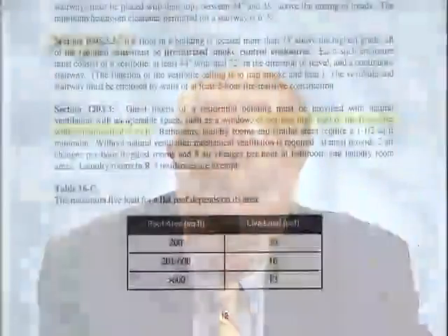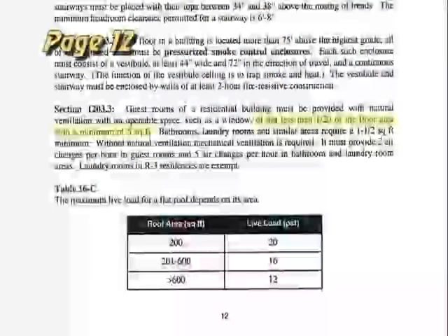Section 1005.3.3 deals with vestibules. Just go ahead and read through that. And then section 1203.3 that deals with the natural ventilation in a room. There are, again, certain minimums required. For example, if you have a 100 square foot room, you need to have at least 1/20th of that in natural ventilation area. 1/20th is in the second line of the paragraph. Make a little highlight there. And the minimum has to be 5 square feet.